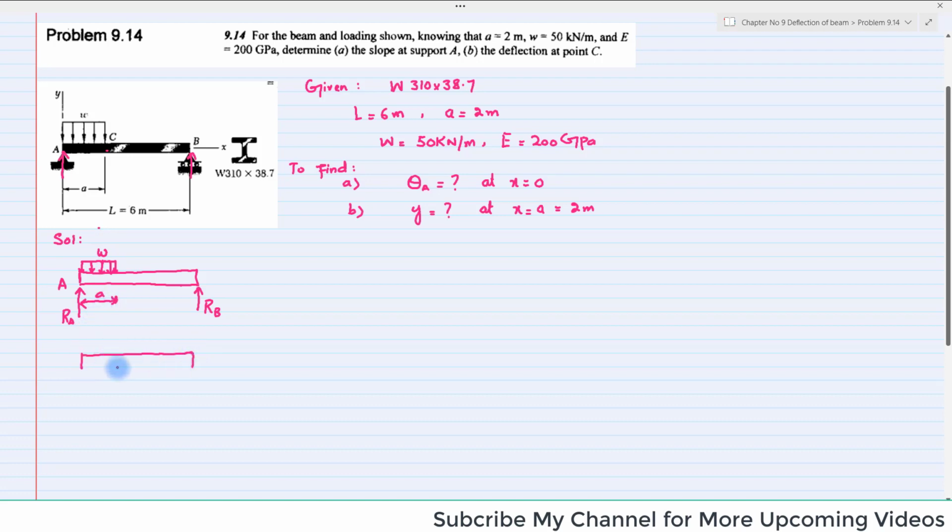This is the same RA, this is RB. Clear? And this w will be converted into point load, w into a, and it will be acting at a distance of a by 2 from this point A. Clear? So now you can apply equilibrium using the free body diagram.